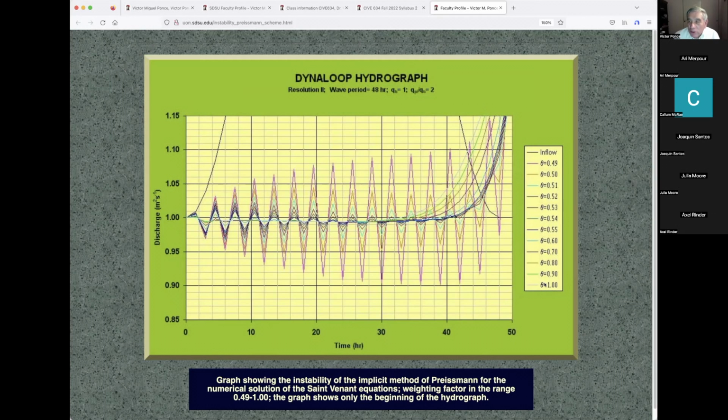So the ideal situation here is to compensate. Don't use 0.5, because you won't be able to run it with 0.5; there will be too many oscillations. But if you run it with 1, it will cut the peak, and you don't want that either. So you settle for 0.6. 0.6 is the number that people settle on.